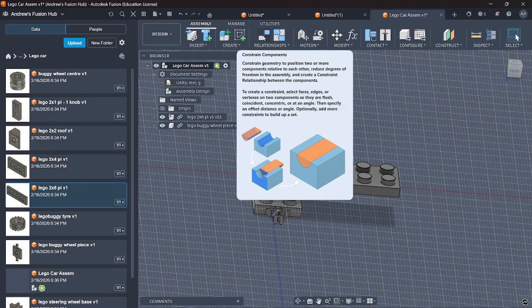The joint feature usually requires you to select edges and stuff like that. And in my opinion, it's not great to select edges when you're CADing, when you're making assemblies, because those edges typically change, especially when you're finishing a part and you want to make it nice and pretty. You're going to start throwing fillets and chamfers everywhere, and then you're going to delete that edge. And when you have a joint in relation to that edge and you delete it, then your assembly breaks.